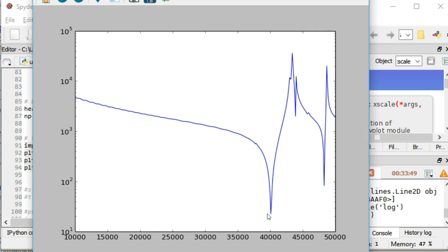We can see the impedance is about 20. However, this is in steps of 100. Whereas in order to get the true impedance and not to miss a value, we would probably need a step on the order of 10 to even 5 frequency intervals. But that wouldn't be possible for the large range we use. Because we're measuring the large range, we use a slightly larger frequency interval, about 100, which took a couple of minutes on this function generator.